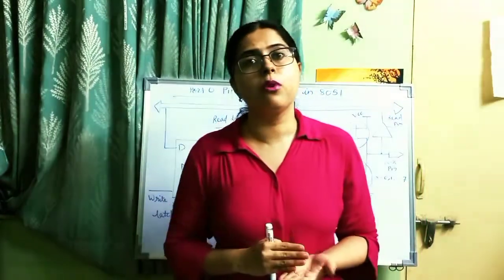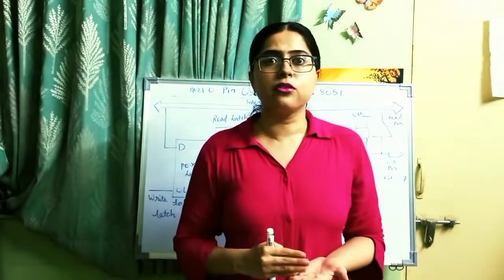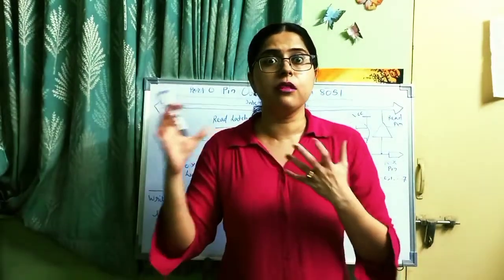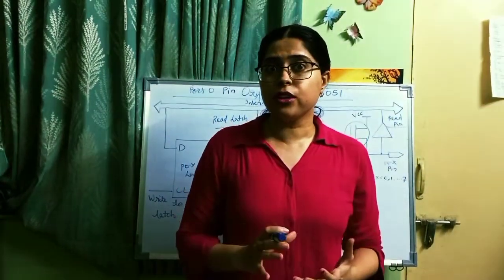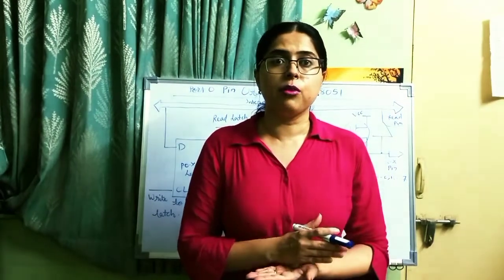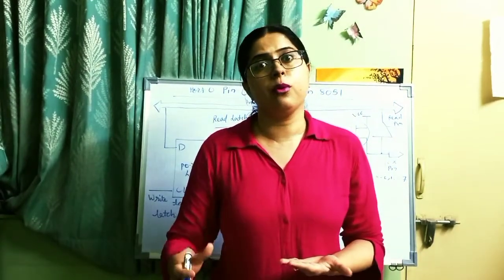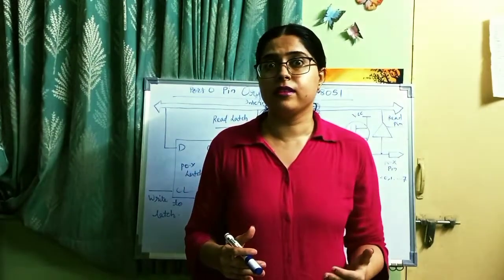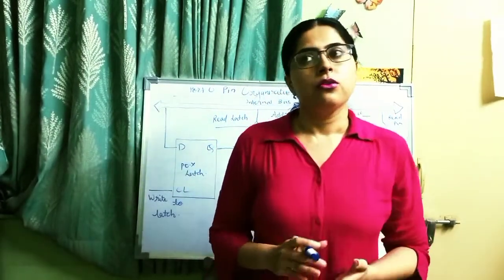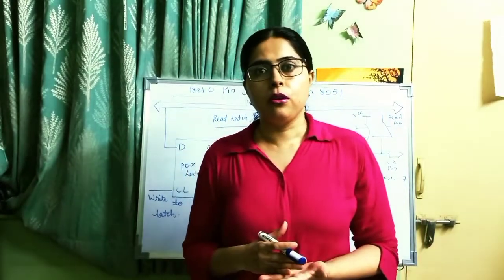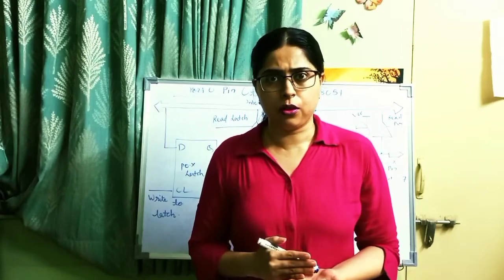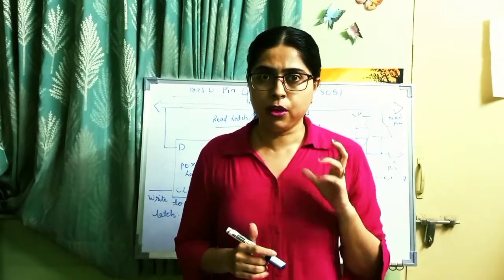In the normal mode, the port 0 pins act as a normal input output port. You can use it for normal operations. But when external memory is interfaced to the 8051 microcontroller, port 0 works in the second mode, that is address data multiplexed mode. We have seen this in the previous lecture, memory organization of 8051. So port 0 acts as the address data multiplex bus in external memory operation.